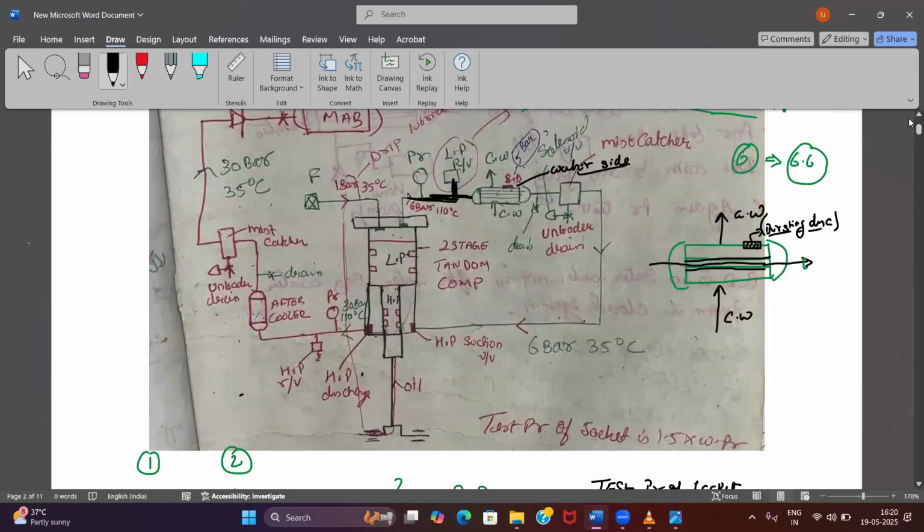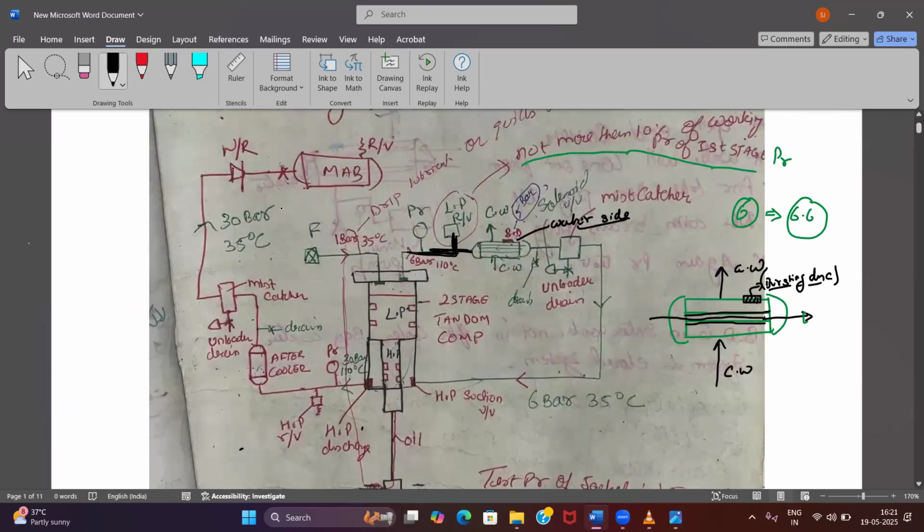Suppose in this system an air high temperature alarm is not given on board, then there will be a fusible plug in this line, and this will be draining outside your engine room. Okay, is it clear? Yes sir. It is going to fuse at 121 degrees Celsius temperature.